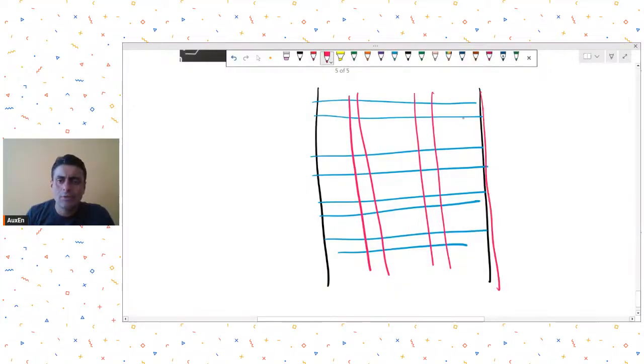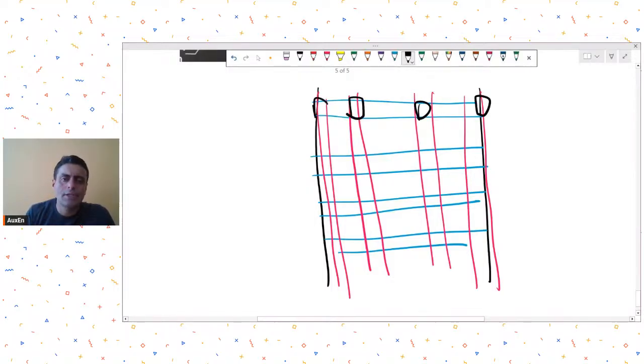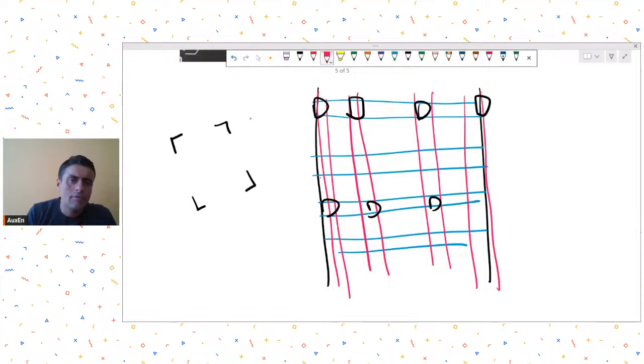And then you will have these primary members supported on columns. Those columns we usually make out of built-up sections. So usually there will be four angles. We make four angles like this in plan view, and then we tie them up with lacings.